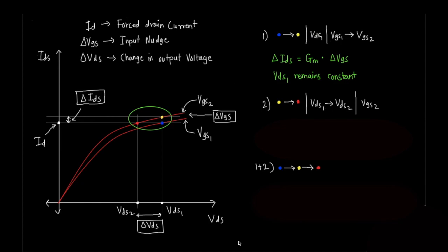Since the final current through the MOSFET will be the same as the initial current, VDS reduces to roll back the current to the original value. This is kind of a chain rule. The first part of the chain is that IDS increases, the second part of the chain is that current is sucked in by someone and the current returns back to the original value. Please pause, ponder and understand this enough.